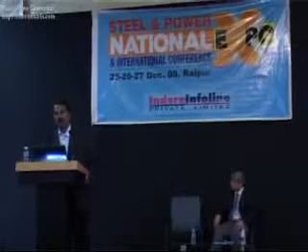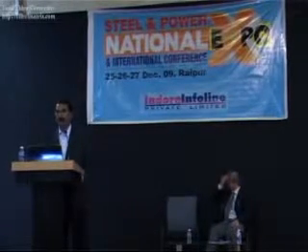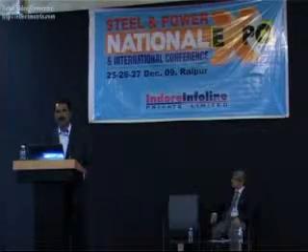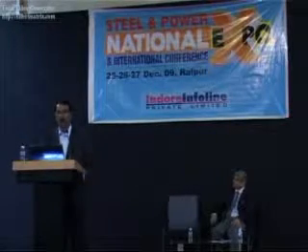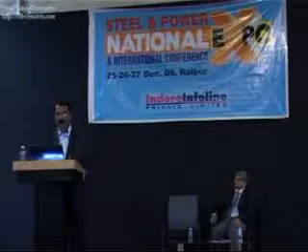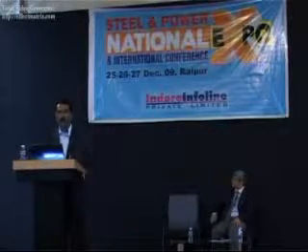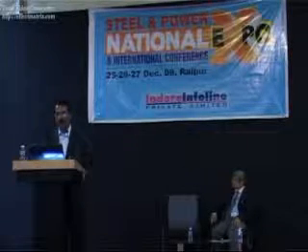As we all know, if water is left untreated, it will have three major effects. It will corrode the system, corrode the equipment. So corrosion is a big problem in any cooling water system. Second is deposition, and third is microbiological contamination or fouling.